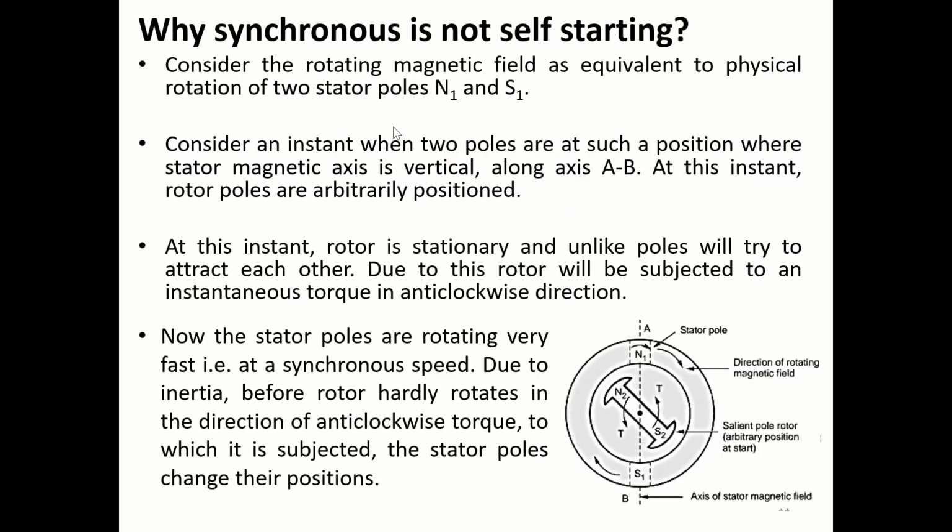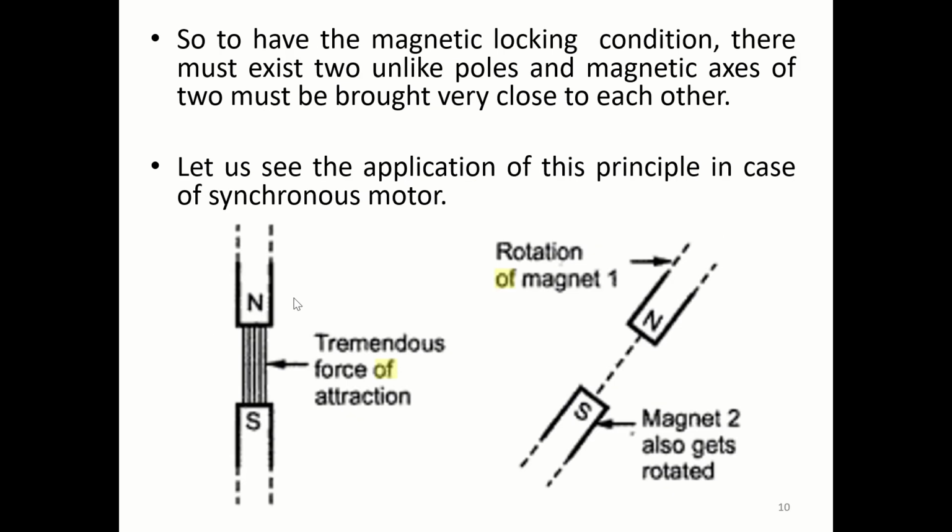Then the most important concept: why the synchronous motor is not self-starting. When supply is given to the stator winding, it produces a rotating RMF, whereas initially the rotor is stationary. When there are the same poles, they repel each other and do not attract. To overcome this, we can use damper winding, and there are several methods. This is one of the reasons it is not a self-starting motor.